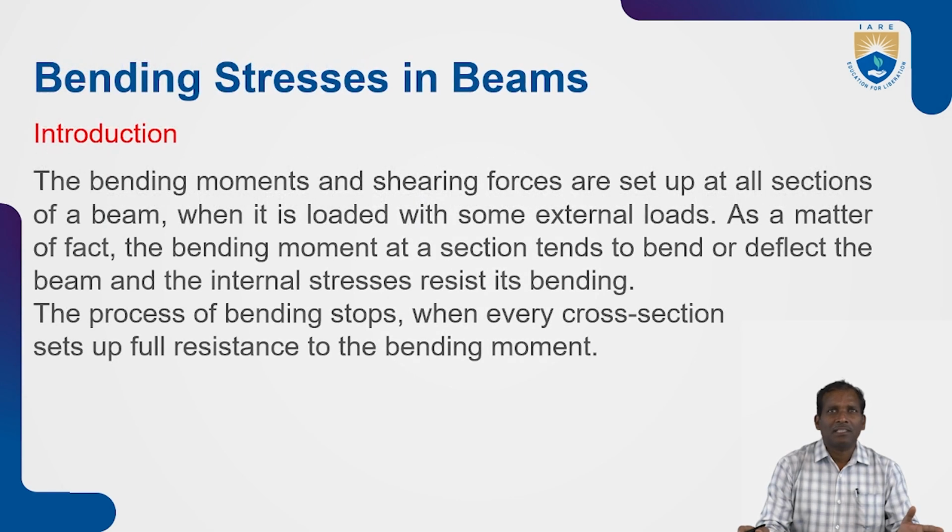So what are bending stresses in beams? Recall the previous session: the bending moments and shearing forces are set up at all sections of a beam when it is loaded with external loads. The bending moment at a section tends to bend or deflect the beam, and the internal stresses resist its bending.